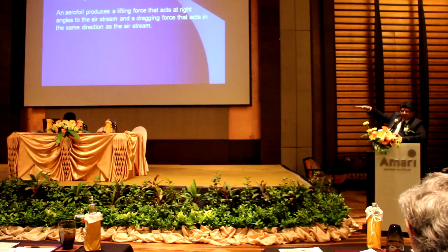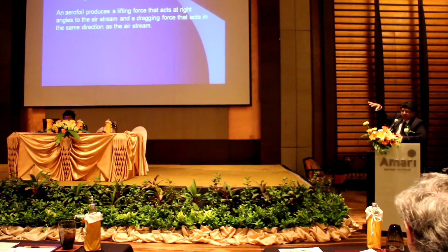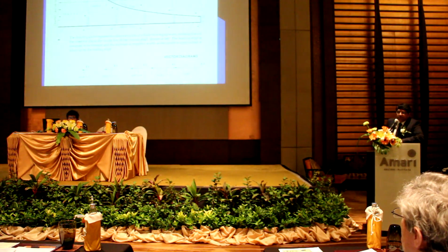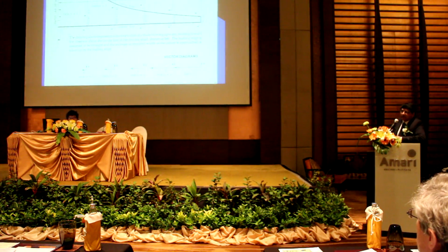So when the thrust or the aerofoil lift is being made to act downwards, there is an opposite suction of the airflow, and hence the fan sucks the air and pushes it through the forced draft or the induced draft fin fan cooler systems. So this is where the aerofoil design is most important, to be able to get the actual lift or the airflow.